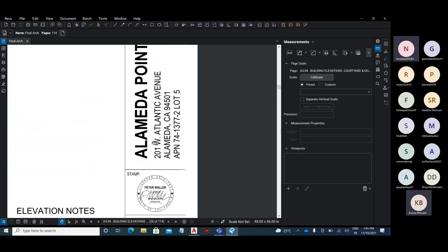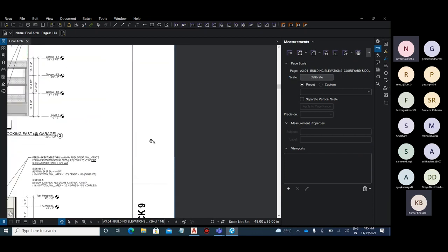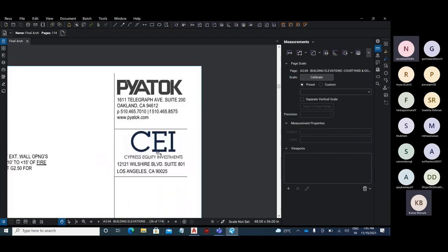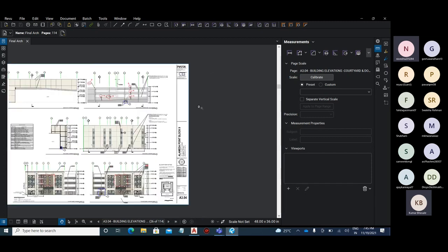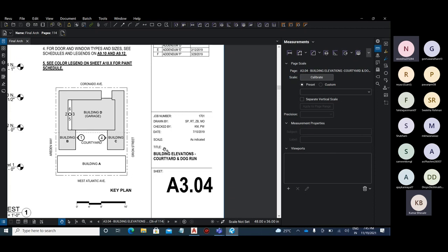Over here, what is not going to change? Let's say over here logo or the project name, it is not going to change. Over here also, if the companies are same, so this is not going to change. So things that are not going to change, you can keep it as a text. No need to create it as an attribute, because this is going to be same throughout all the sheets. Is this point clear to everyone?